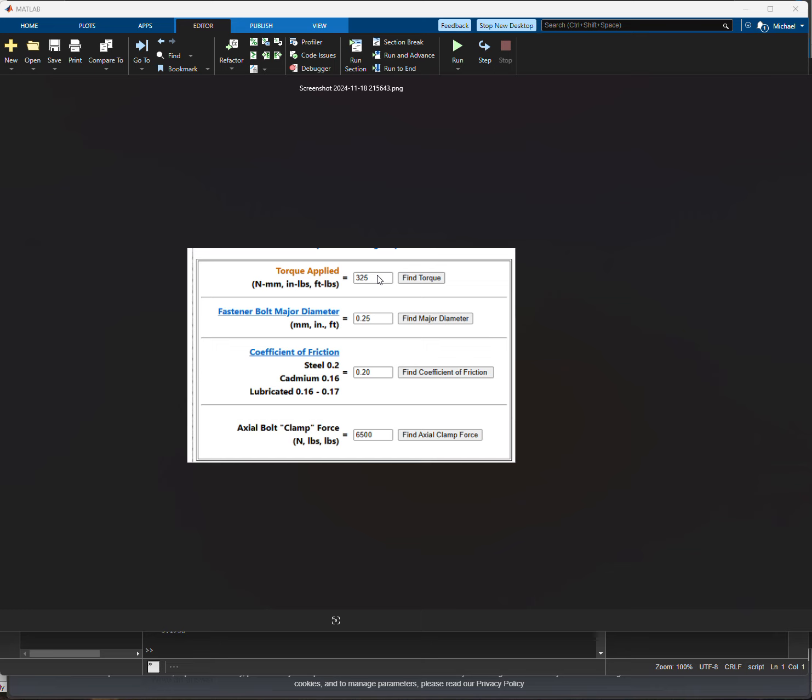What I mean by that is when we tested the ER11 collet, we hit 200 inch-pounds of torque, and that seemed somewhat substantial to me. I do feel like if I added another 50% more force than what I was tightening that collet nut down with, I could probably strip out a set screw.